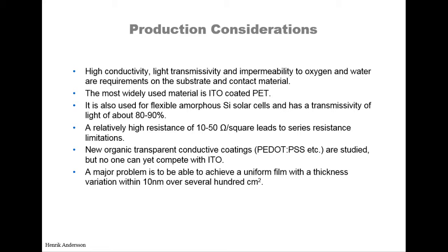New organic transparent conductive coatings are studied, but no one can yet compete with ITO. A major problem is to be able to achieve a uniform film with a thickness variation within 10 nanometers over several hundred square centimeters.